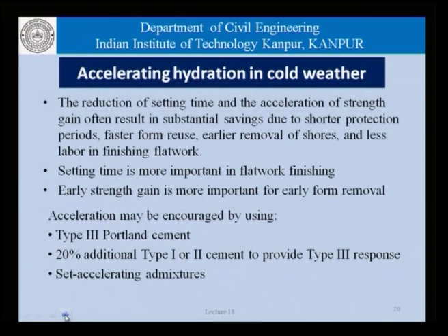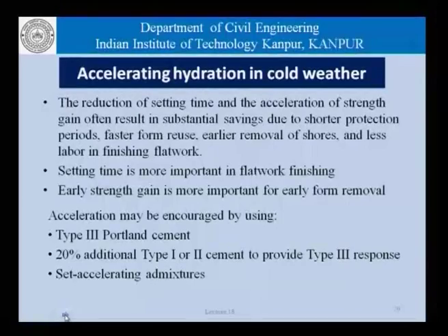The setting time is more important in flat work finishing. Flat work finishing refers to structures such as highways or slabs in multi-storied buildings and so on. Early strength gain is more important from the point of view of form removal. The economics still remains the same.